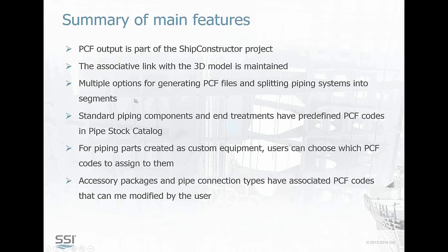Pretty standard stuff. Standard piping components and end treatments have predefined PCF codes in a pipes.catalog. Depending on how you use them, you may want to adjust those S keys, as Zoe also demonstrated. For piping parts creation as custom equipment, users can choose which PCF codes to assign to them, as she demonstrated. Finally, accessory packages and pipe connection types have associated PCF codes that can be modified by the user. So we tried to create a fair amount of flexibility in this product, understanding that in the real world the application of using PCF does require that kind of flexibility.